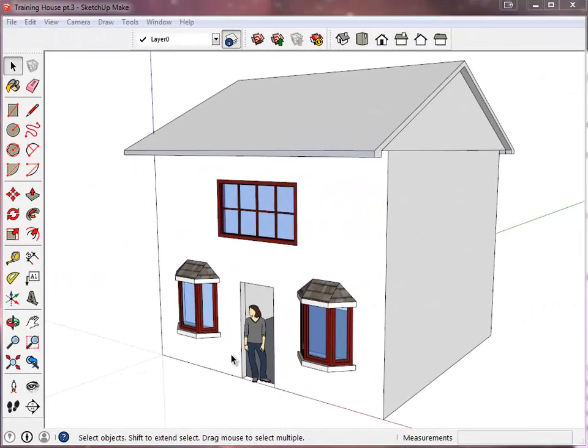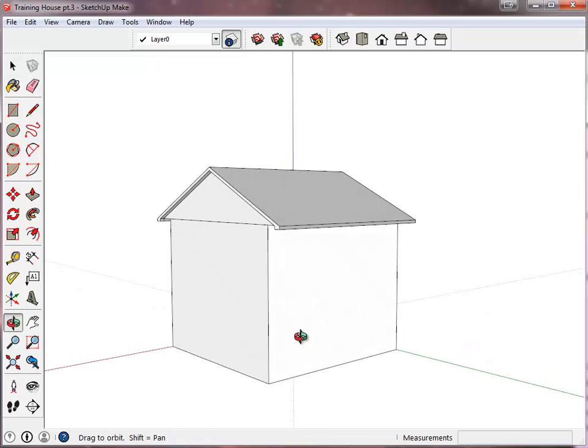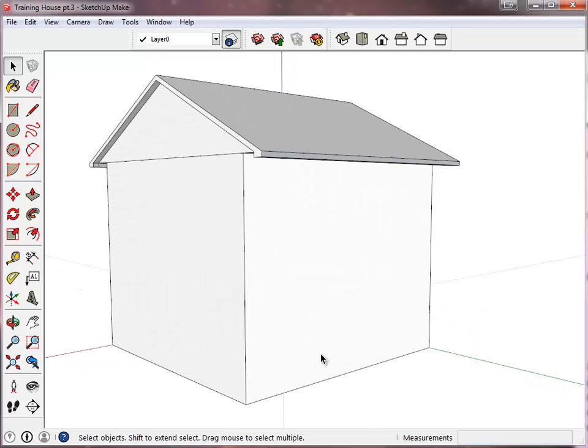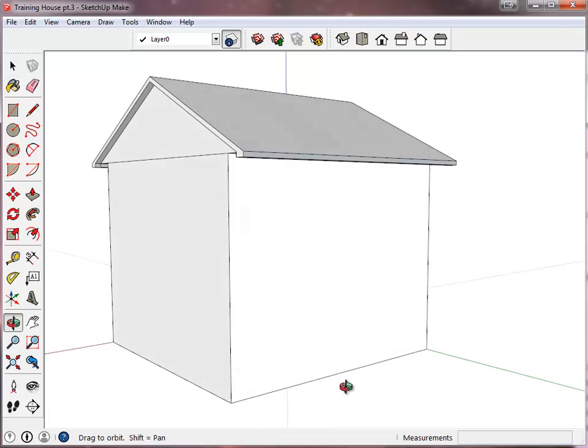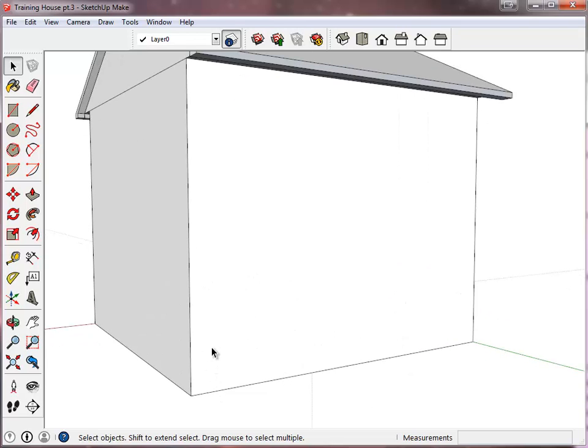Now that our windows are completed, we will begin to work on a deck off of the back of the house. To align the deck to the house, we will be using lots of dimension lines. When you use these lines, make sure that your lines are on top of the face itself and not going off in another direction. These lines are crucial to ensure that the drawing is lined up properly and in the right position.